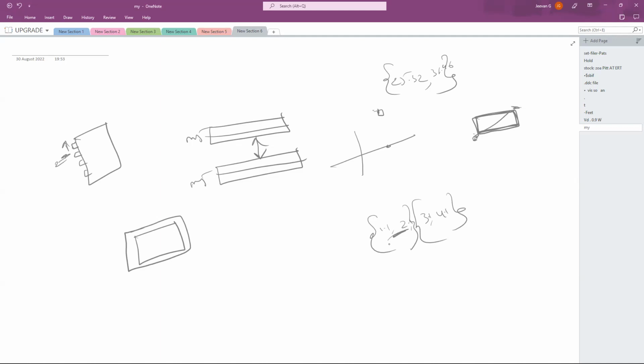But for example, in my previous project, I had one RAM like this. So why are we not allowed to route any metal layers? Because inside this macro, the pins were like this. These are some 3 to 5 pins, P1, P2, P3, P4, and P5. These pins were routed on the M5 metal layer. All these are M5. So if we allow the tool to route over this macro, then this M5 will be shorted, right?